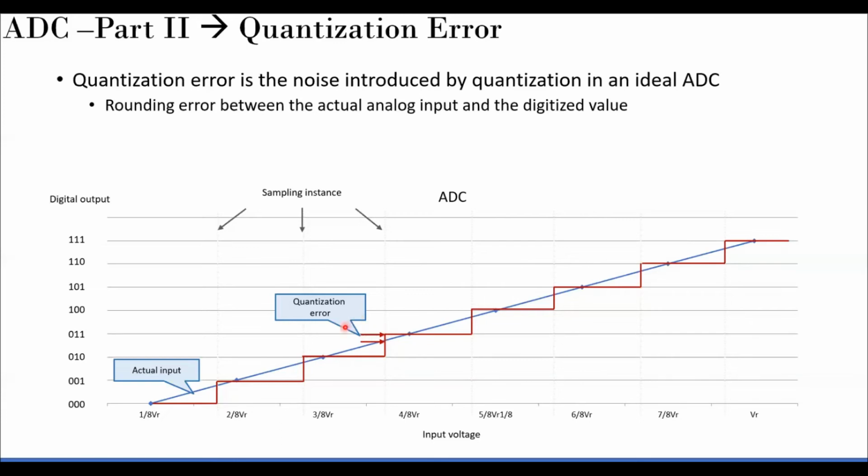This quantization error is important because it induces noise in the signal. So when you sample in time or sample in amplitude, you are inducing an error. Always remember that. Uniform quantization typically means you use a round operation to the closest value, and there is an error associated with it. You will study in detail in DSP how to quantify that error. And the higher the number of bits, obviously you'll have finer levels and less quantization error. So you typically want as many bits as possible.